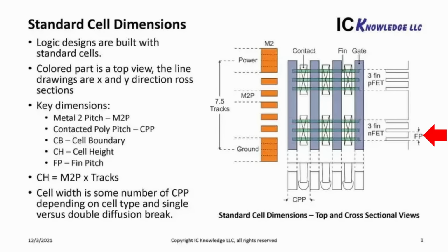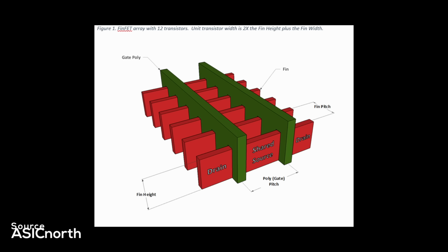In the past, FinFET process node scaling was achieved by reducing the so-called fin pitch, how close the individual fins are to each other, and the gate pitch, which determines how close the gates are to each other. If we look at a 3D representation of FinFETs, we can see that fin and gate pitch are related to the size of the structure. If we reduce these, we can pack more transistors into the same area, thus increasing transistor density.